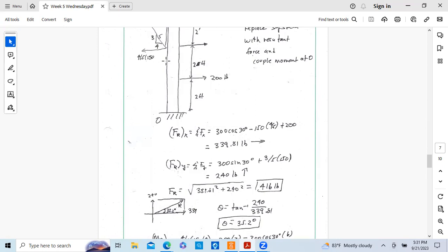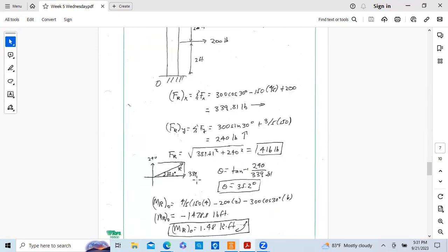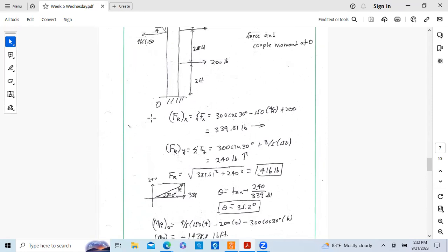Position it somewhere in here that creates this resultant moment, at some distance. And again, the only component that creates the moment is this resultant X force. The Y doesn't. It passes through here. I didn't do that, but you could actually position that to have only one force acting on here, and it is the same as this force and moment acting down here.